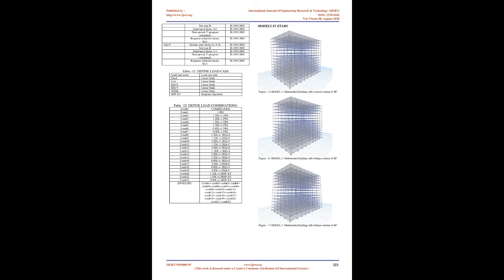Then after that, study the concluded models again after modification to the dimensions of cross-sections of some or all structural elements: beams, columns, slabs, oblique columns. Then the processes of analysis and design are made and new models are concluded, and so on until reaching the final models in which all structural elements achieve design code conditions as well as lower cost.